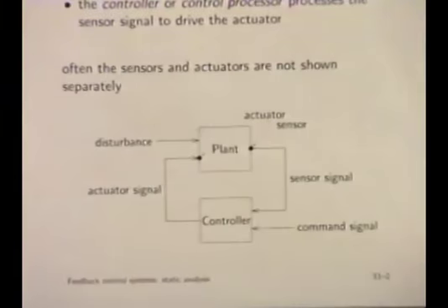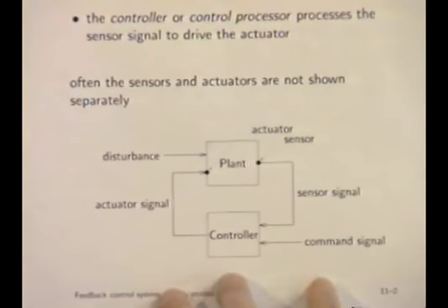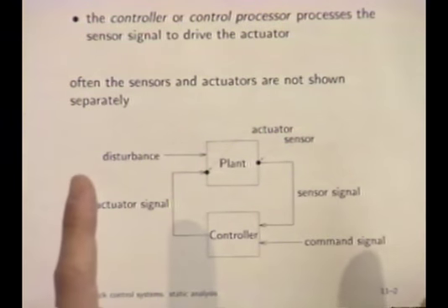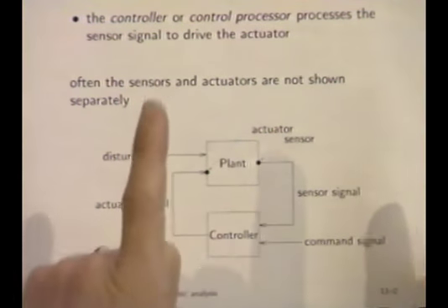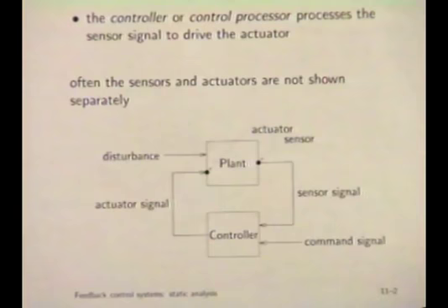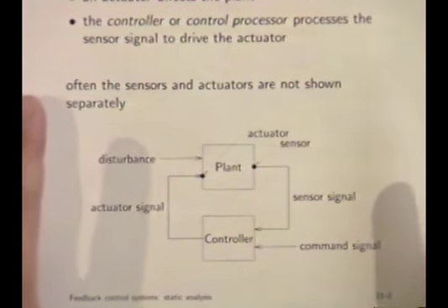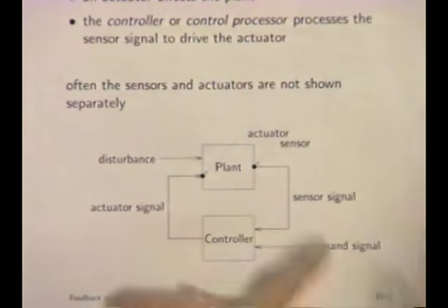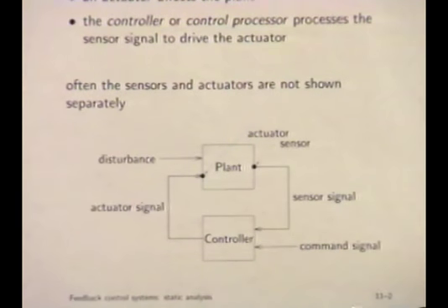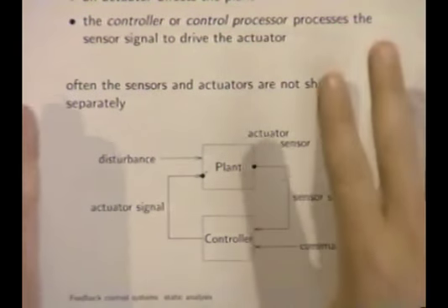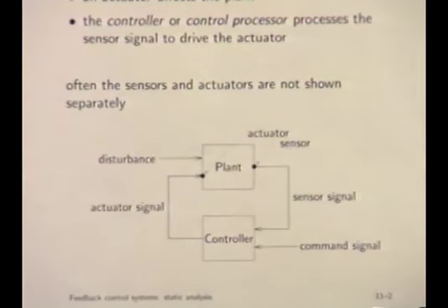Classical examples would be something like an electromechanical system, like a positioner. In other words, a system that, for example, moves an XY stage in building an integrated circuit. There, the plant would be the mechanics of the XY table and probably the motors. The sensors would be all the sensors that tell you exactly where the table is.